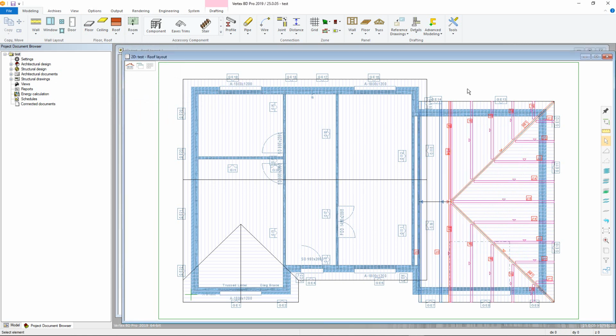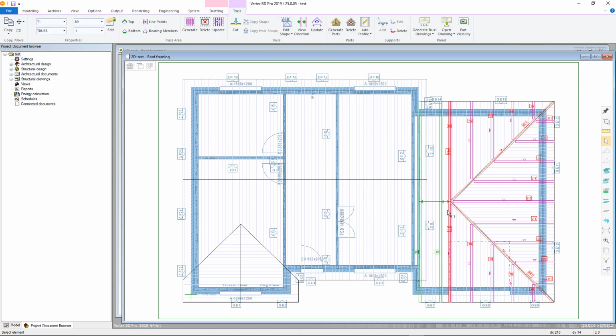It is advisable to do this in the framing model, so press F4 and choose the roof framing modeling pair. The truss layout is still visible. To add the profile, select the trusses. It is advisable to select different types separately. Then right-click and generate parts.